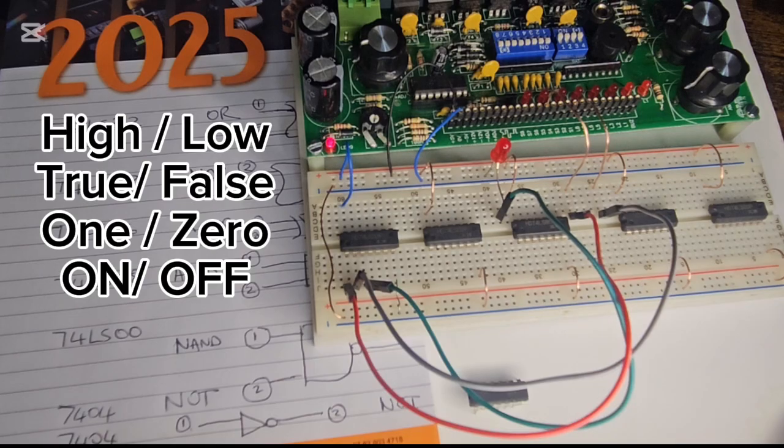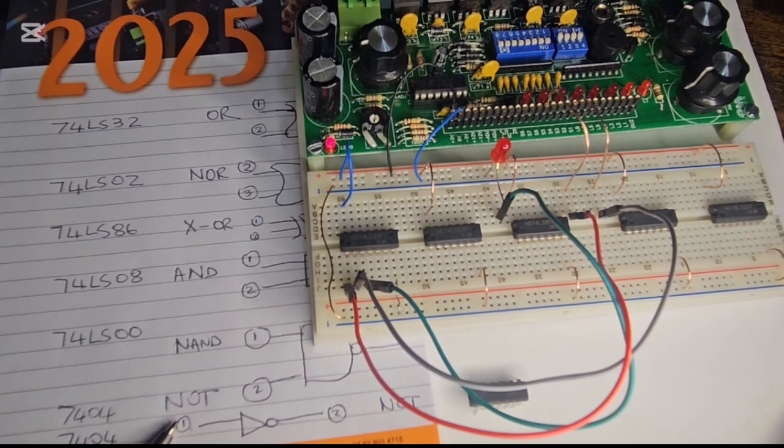So in a NOT gate, if the input is low, the output will be high. If the input is a 0, the output will be a 1. If the input is false, then the output will be true. This is a type of example. When you say if the input is low, let's say if my switch is off, I want my lamp to come on. It's a NOT, it's an inverting.